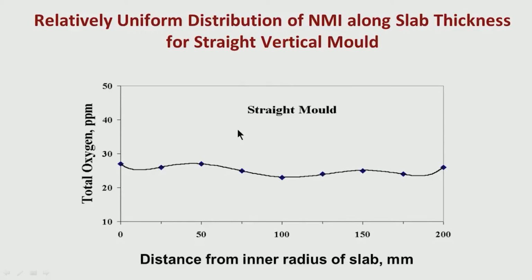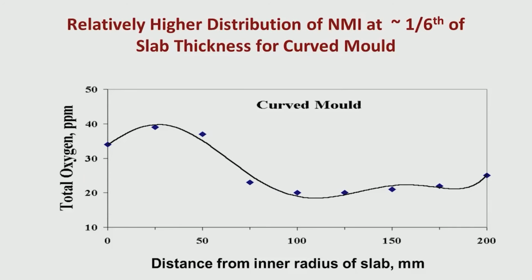If you have a good inspection facility, then you can find out at what stage these defects are coming out and what the distribution of the defects is, like whether defects are coming more on one surface or near both the surfaces. If you roll this slab, we will find that defects are coming more on the surface which corresponds to the inner radius of the caster.